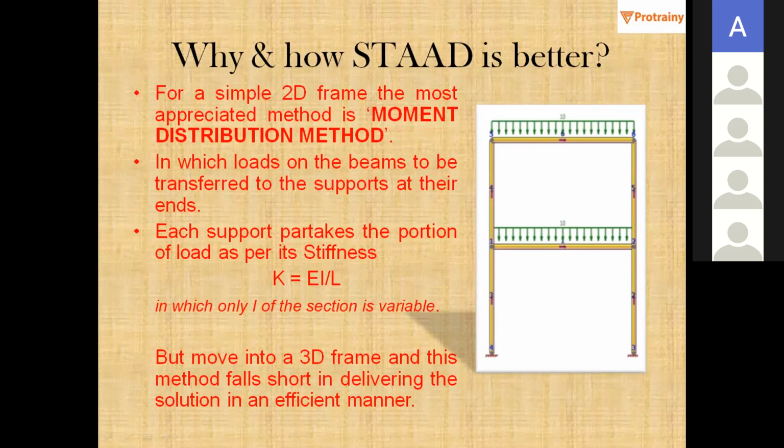By applying all these variables, you can solve this kind of frame. But if the condition is that it has to be a 2D frame, moment distribution method or any of these handheld methods, you can't apply them on a 3D frame. Second, for example, let's assume that this structure, this frame, is 10 stories high. Just imagine how tedious your job becomes. So again, this moment distribution method is only good for a 2D frame.